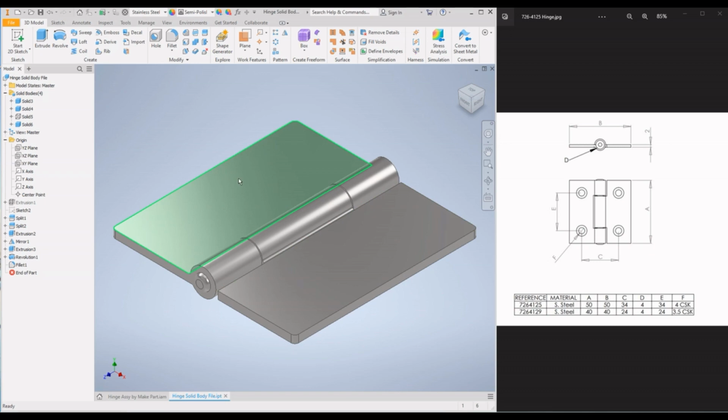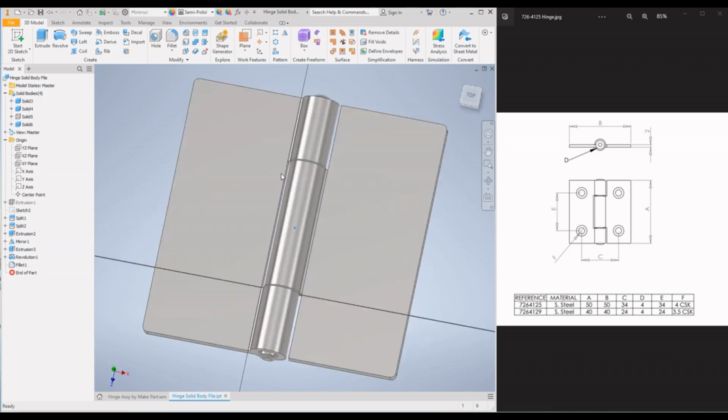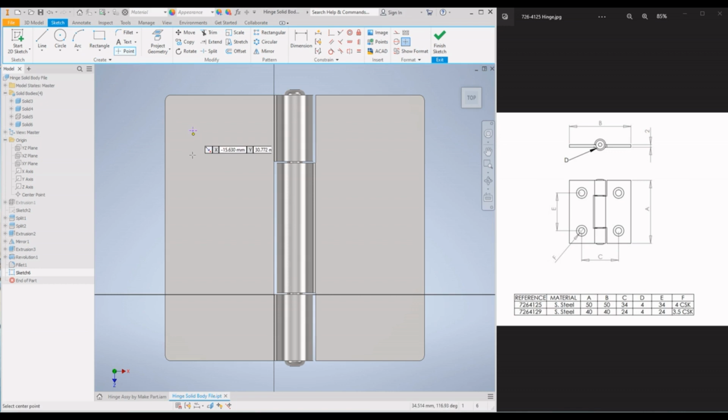In order to do that, click on this surface and add sketch, and use point, create 4 points at 4 corners. Let's add a few constraints: horizontal constraint between these 2, and horizontal constraint between these 2, and vertical constraint between these 2 and these 2 as well. Now let's add some symmetric constraint. Click on this symmetric constraint command and click on this point and this point.